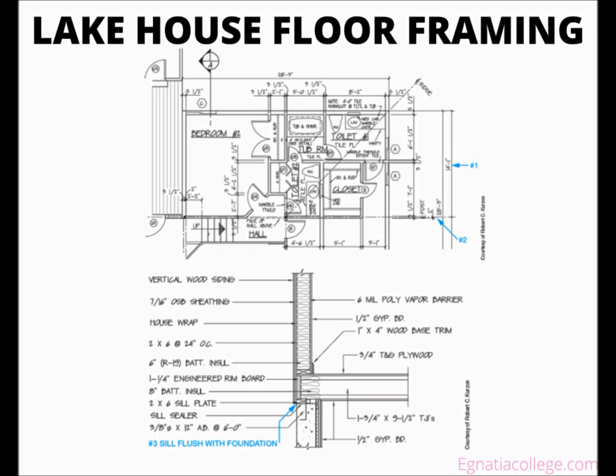The inner ends of the remaining floor joists in the lake house are supported by bearing walls in the lower level. For example, some of the kitchen floor joists are supported by the west wall of the playroom, near the fireplace, and some by the LVL beam that spans the distance from the playroom wall to the foundation in the crawl space. The size and spacing of material to be used are given on the framing plan by a note.